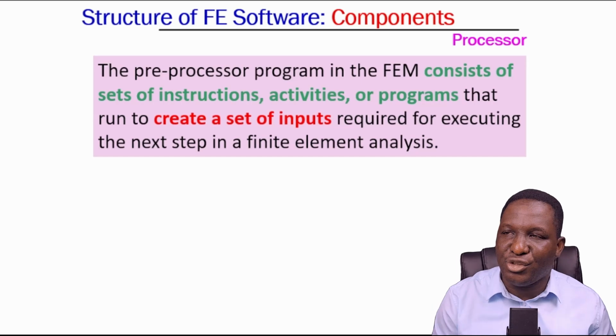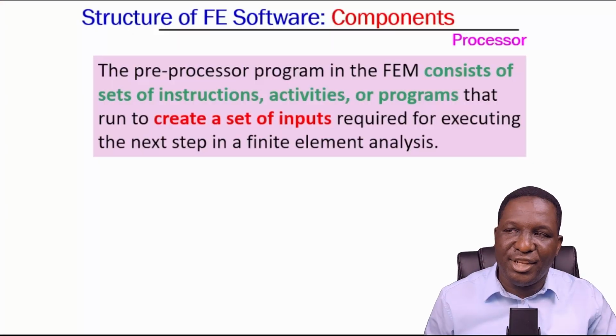And what I mean by this is basically at the preprocessor stage, you're trying to generate as much information as possible to advise the simulation engine of what to do next. So for example, if you want a certain final mesh to be executed in your model, that's what you do at the preprocessor stage. You refine the mesh, and then that information generates a new mesh, which then passes that information to the simulation engine. And we take that information to now inform what happens once you get into the simulation engine.